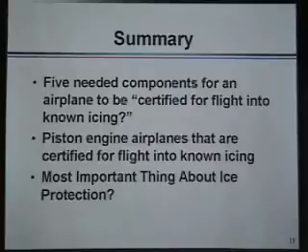And I'm getting this information from a NASA aircraft icing expert. He gave a seminar here on campus 5 or 6 years ago, and this was the most important thing he said that day: piston-powered airplanes, even if they're turbocharged, are not as overpowered as turbine-powered airplanes are, so the margin of how much extra power you've got is essentially zero. You've got to get out of the icing conditions as soon as possible. So if you get into known icing, use all your ice protection systems, but most importantly, leave the icing conditions. Get out of the icing conditions as soon as possible.